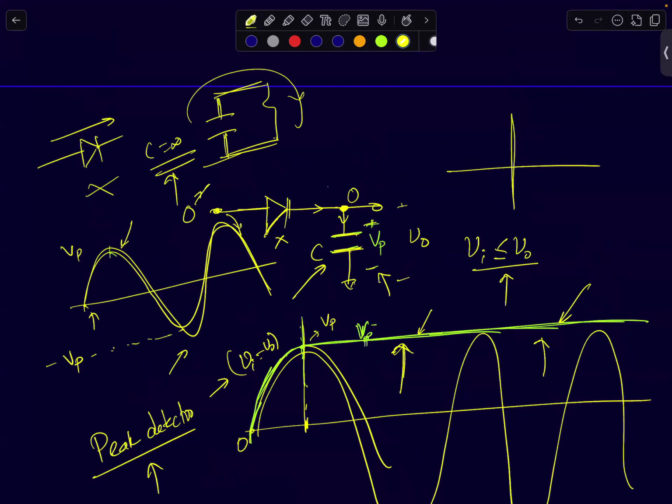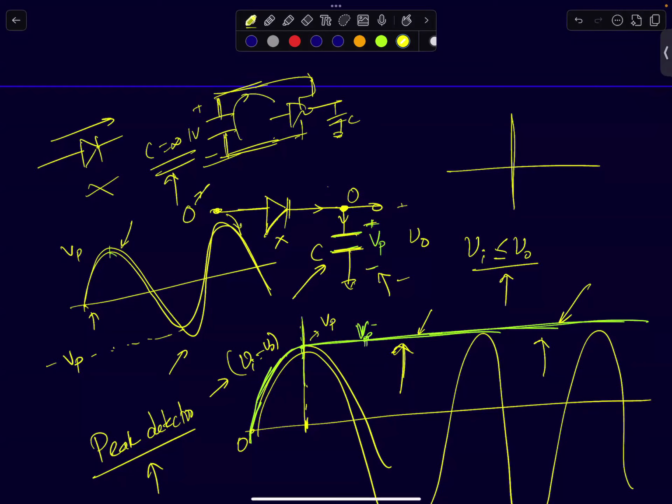You can picturize it as a capacitor with infinite capacitance. Okay, which means it has boundless charge. If you store some finite volt, 1 volt across this, then the charge stored is infinity. It has an unlimited amount of charge. So whenever you are connecting any circuit, your circuit will draw some power. Let's say your CMOS inverter is drawing some power for it to run. Every cycle it will charge its local nodes, right? Half CV square power or CV square power. It'll absorb, and all that power will keep coming from this capacitor, the ideal capacitor. So I'm just giving a hypothetical understanding of a voltage source.